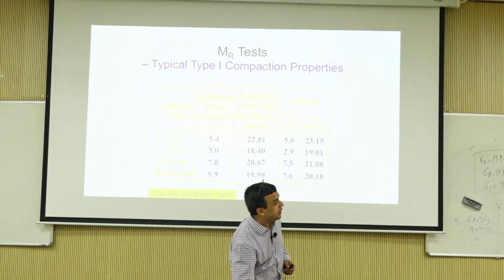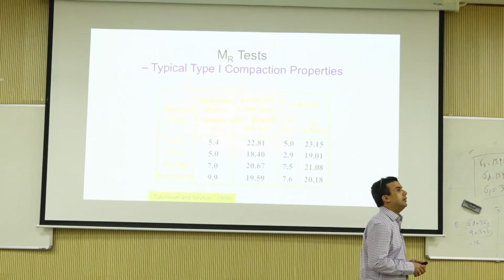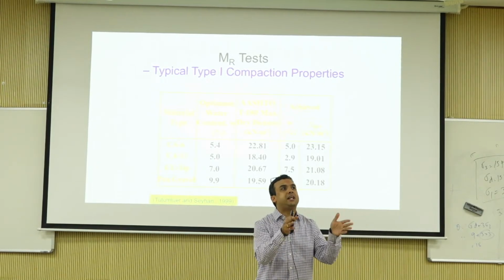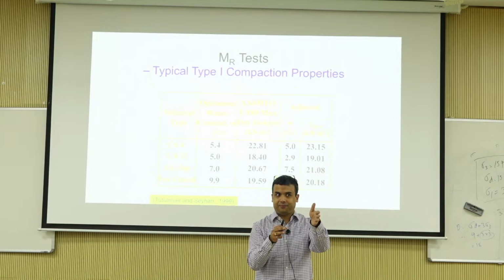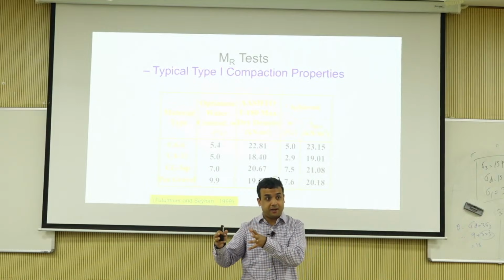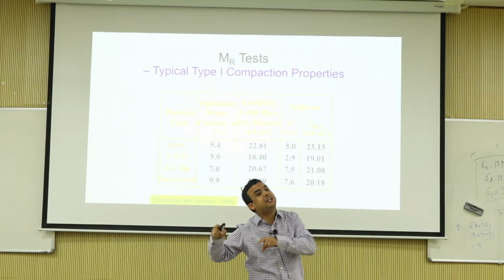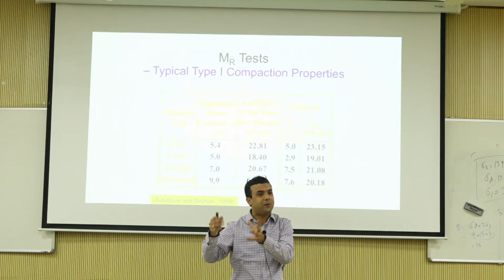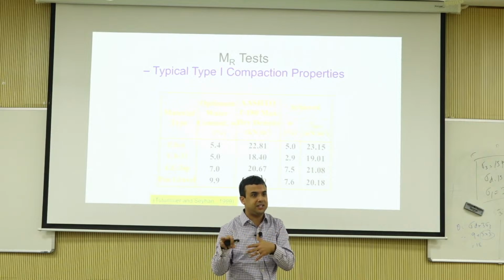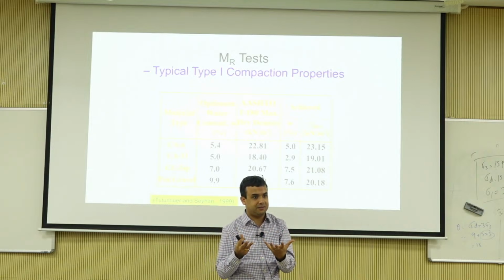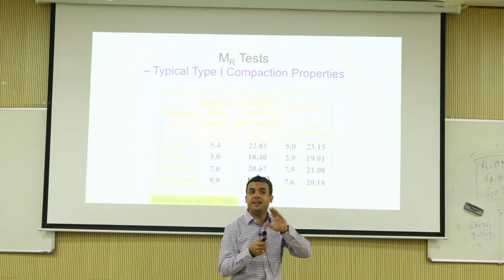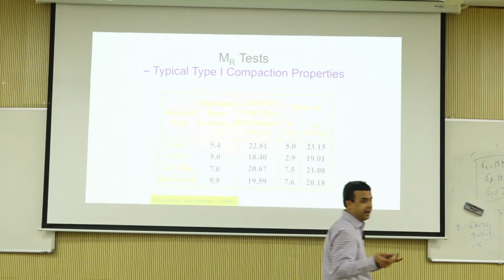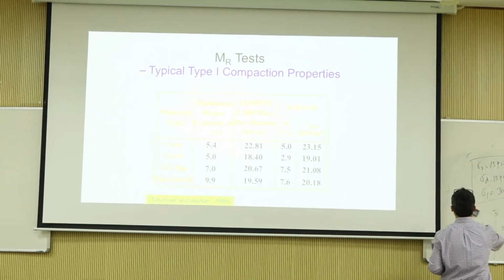Okay. Good question. Will the resilient modulus change between the two test procedures? Probably yes, right? Because now it is much more shaken down. But what is more representative of what is happening in the real field? Their argument is that the higher torture one is actually more representative because you are shaking it under bigger stresses. So that's the reason I said it's not a specification test, right? It's a research test. So maybe the numbers are different. I don't have the comparison.